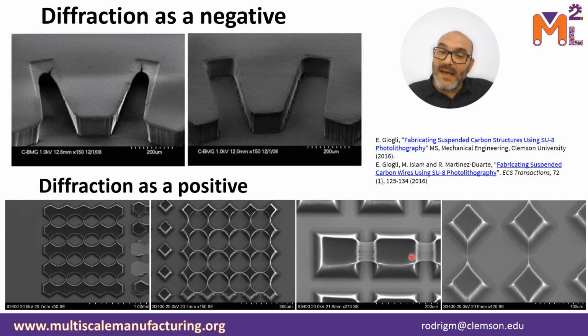So depending on that, you could actually start determining whether you get a plate or a bridge, or you can start getting a wire, right? So that could be another way to leverage the diffraction, right? So you worry about the gap between the anchors, right? And also the gap between the mask and your photoresist layer, right? So again, I encourage you to check these two different references, and if you have any questions, feel free to reach out.